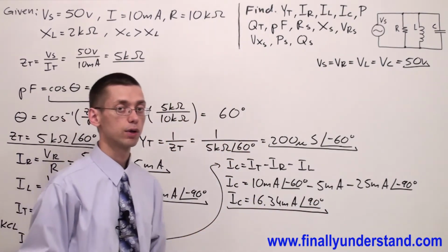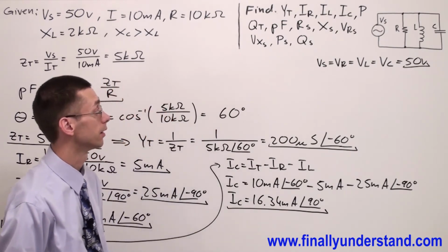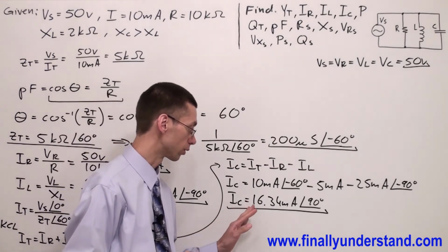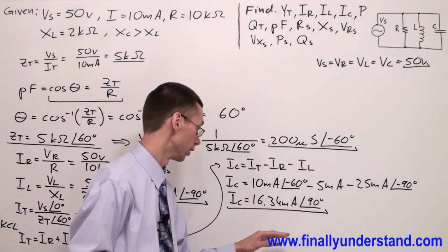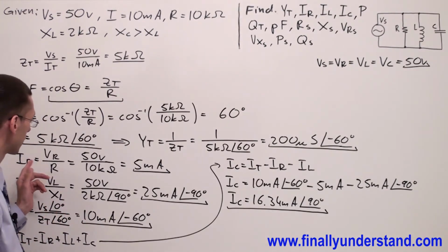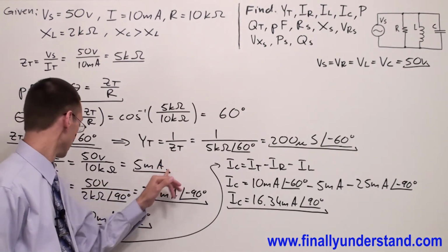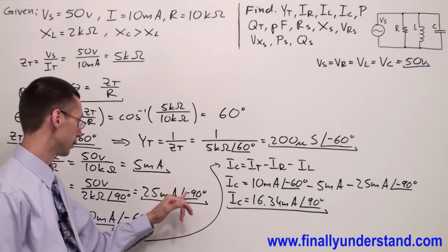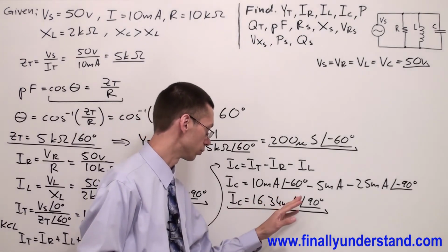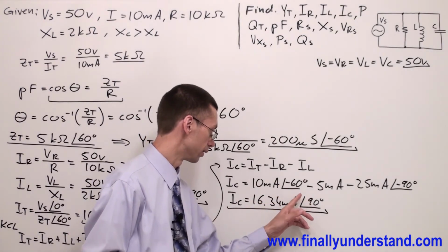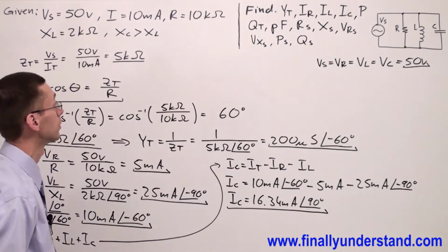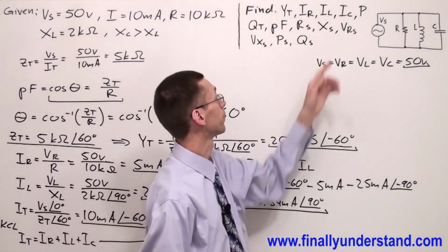Anytime you are going to calculate the currents in the RLC parallel circuit, you're supposed to always look at the angles, right? Make sure that the resistor is going to have current with angle of 0 degrees. Inductor is going to have angle negative 90 degrees for current, and IC is going to be with angle of 90 degrees. This is very important. So I found all currents.